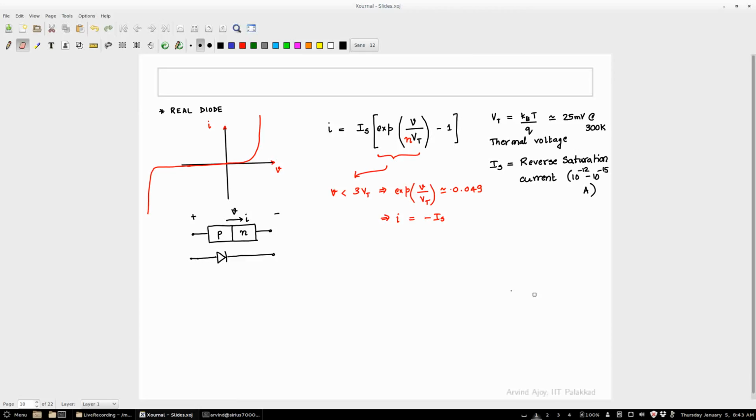So if one energetic electron comes and collides with the lattice, it can, for example, generate an electron and one hole. So charge-wise, nothing has changed. Now if it is sufficiently energetic, the secondary electron which is generated can have sufficient energy to go and knock out another electron and hole. And each of these can go and knock out another electron and hole. It's like an avalanche, right?